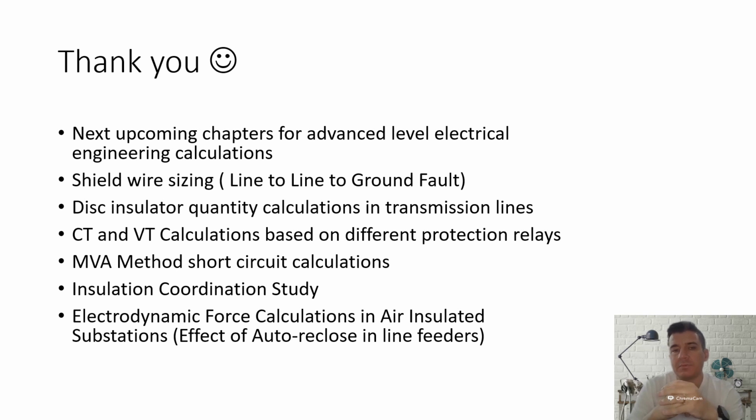So I will try to explain at a very detailed, advanced level, hopefully in the following weeks, these current transformer and voltage transformer calculations. And also if you are working at a medium voltage level with delta connections, what is the required ferroresonance calculation of that burden, that VT. Let's say you will see, okay, 100 volt amps. So where does it come from, and what is the resistance value, and how will we calculate that resistance value for the ferroresonance effect, to prevent this effect, and so on.